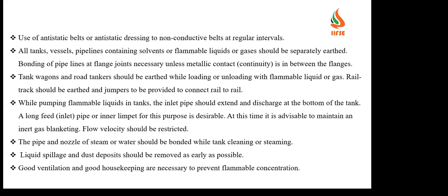Wherever there is a gap in the metallic contact between flanges, wherever there is doubt, there we use these static jumpers for continuity. And tank wagons and road tankers should be earthed while loading or unloading flammable liquids or gases.